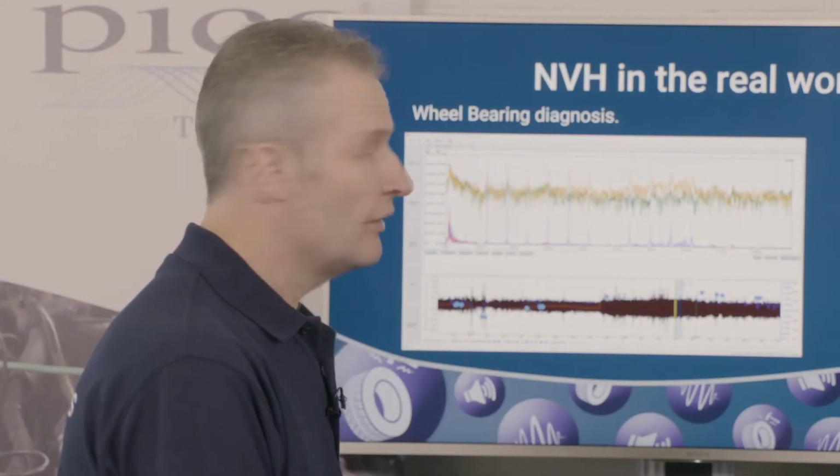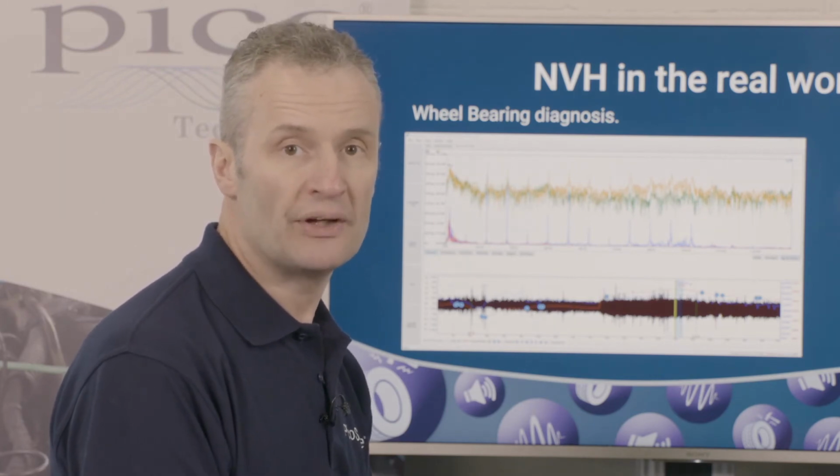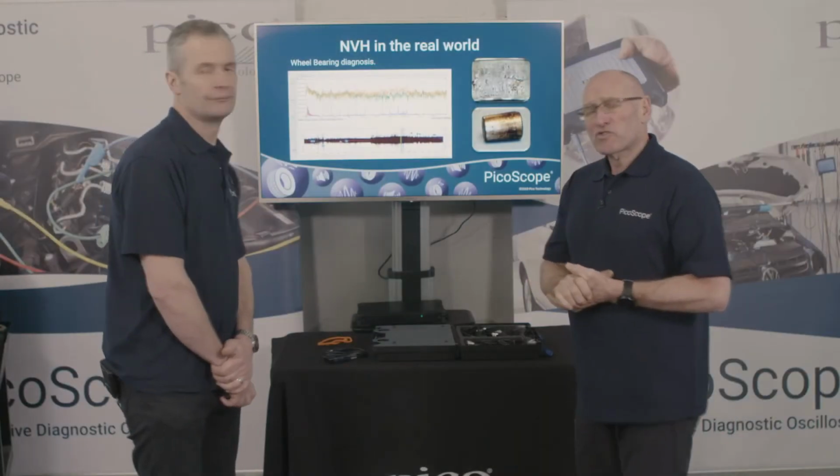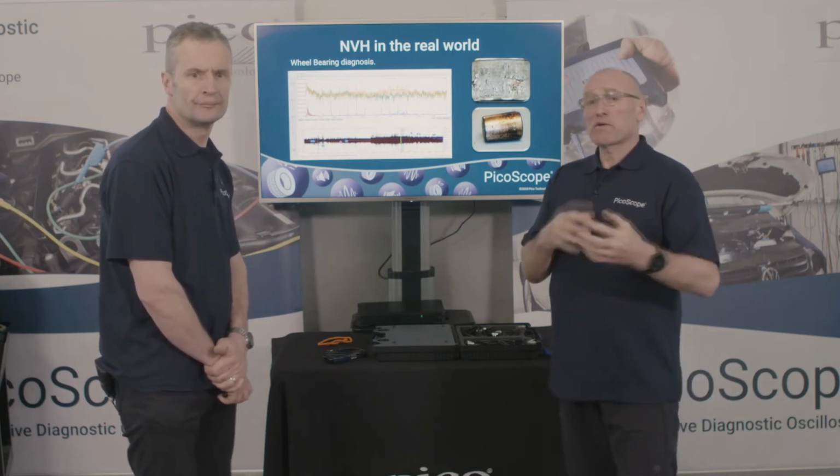But using microphones and accelerometers in conjunction with one another, and listening to the playback and identifying all these unknown peaks within the spectrum, we can make a judgment on which is the offending bearing. I found that quite interesting, because my understanding of a bearing-related fault was that you would have a very narrow band of separation. In other words, frequencies which are quite close to each other, varying by a small amount, would normally represent a worn track within a bearing.